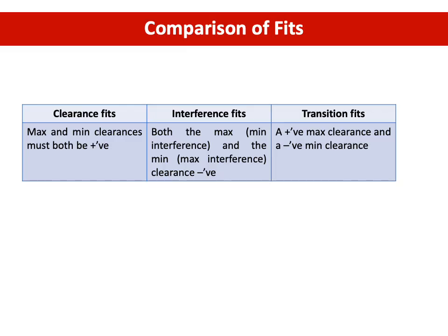So this is showing you the comparison between these three fits. As you can see, for the clearance fit, the maximum and minimum clearance must both be positive. For the interference fit, both the maximum and minimum interference are negative. The transition fit has a positive maximum clearance and a negative minimum clearance. Try to understand all these fits. Read through this note.